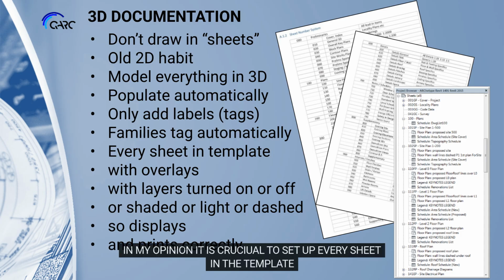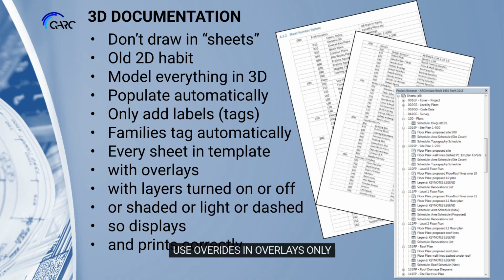In my opinion, it is crucial to set up every sheet in the template with lots of overlays. Use overrides in overlays only with layers turned on or off or shaded or light or dashed, so it displays and prints correctly.